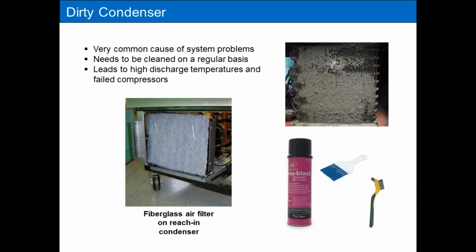So you could spray this chemical on. What I normally do is brush it first with a good brush, get all the heavy dirt off, and shut the unit off. Generally I don't apply the cleaner with the unit running. Shut it off, spray it down, leave it set for maybe 5-10 minutes and plug the unit back in. And if it's really not that dirty, that is a pretty good, effective way of cleaning those coils.